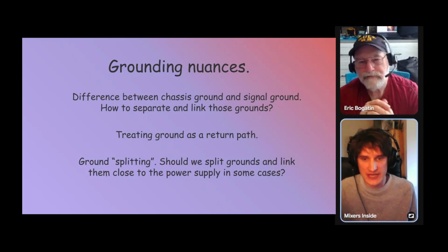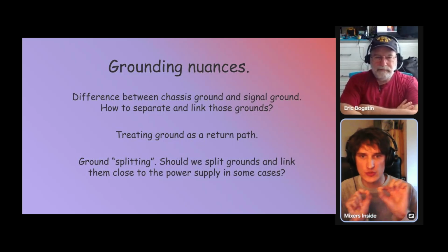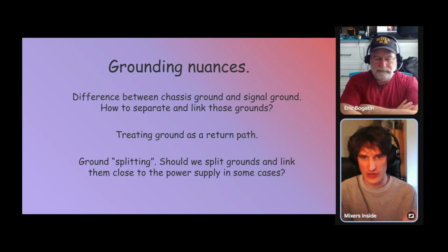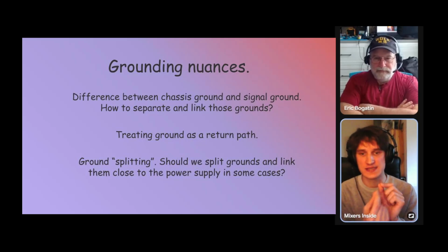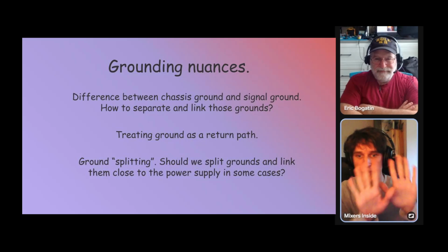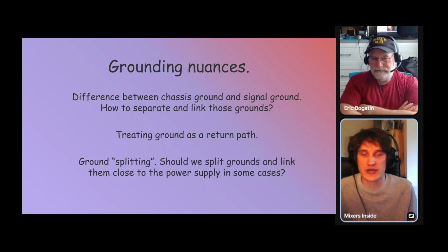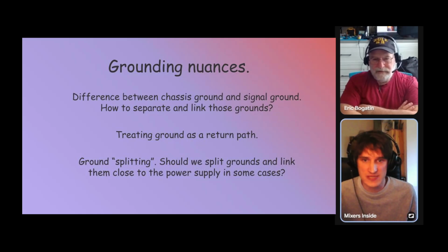And what happens from the EMC perspective when we use a dedicated wire that's exactly connected to the ground node, but applied only for one return current, so it can be shaped not like a plane, but like a single wire? A trace. Exactly, a trace. Can this ruin our EMC performance in some cases?